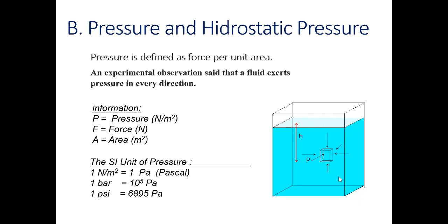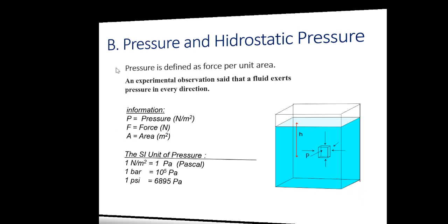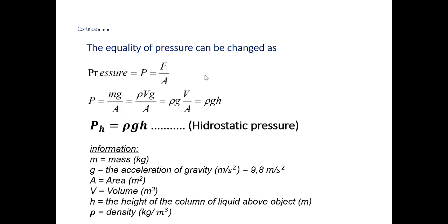And in fluid statics, we always think about downward, the depth. The height in here is the depth. We think about downward as the positive direction, so the deeper you go, the greater the value of h. Okay, so in the beginning, we will have P as pressure is force per unit area.